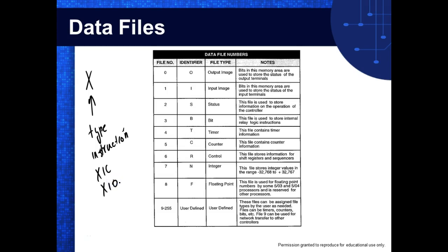I understand that. And then we would put a what? Colon. And then what comes next? Yeah, next comes the slot number. And then the next one is optional, right? You understand? If we have multiple words in a single module, then we would put a dot, right? You understand? And then we would put what? Yeah, the word number, word address, I guess it'd be more precisely.